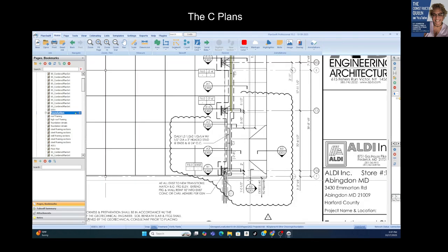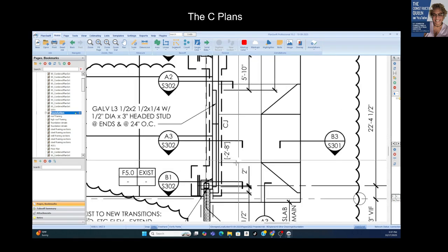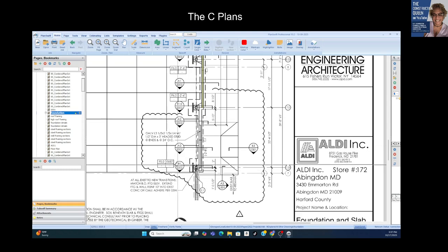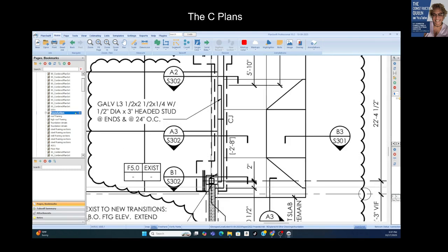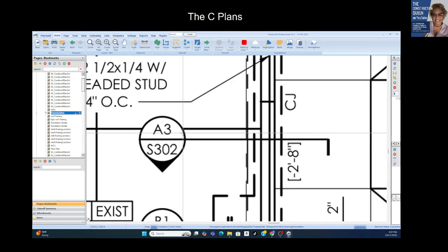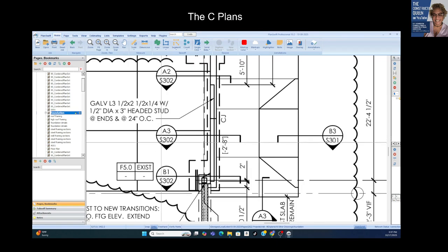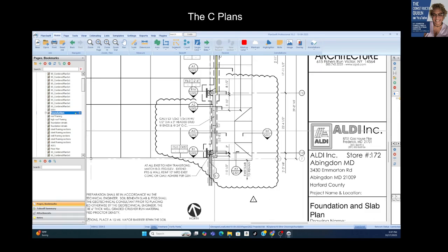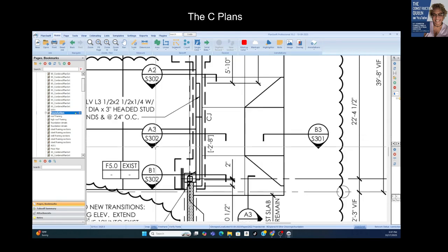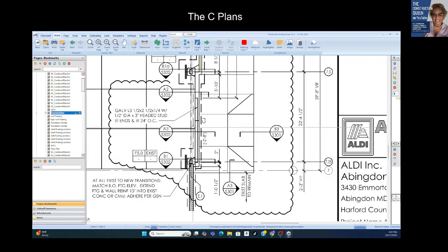And so what we have to do now, if we were going to do the takeoff, we need to know this is a continuous footer of some kind that's going to be represented when we look at image A3 on sheet S302. This is a section view marker, where it's got his little head, his hat, his leg, and his foot. That lets me know that whatever I'm referencing, looking from this direction, it's only this portion of the wall.